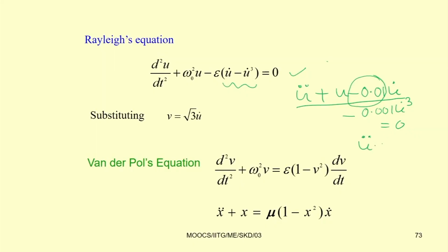There your equation is u double dot plus omega n square u plus 2 zeta omega n u dot equal to 0 for free vibration, or for forced vibration it is equal to f sin omega t. Here the coefficient of 2 zeta omega n what you have studied is positive. So, if you have a negative coefficient, in that case the response will be unstable.